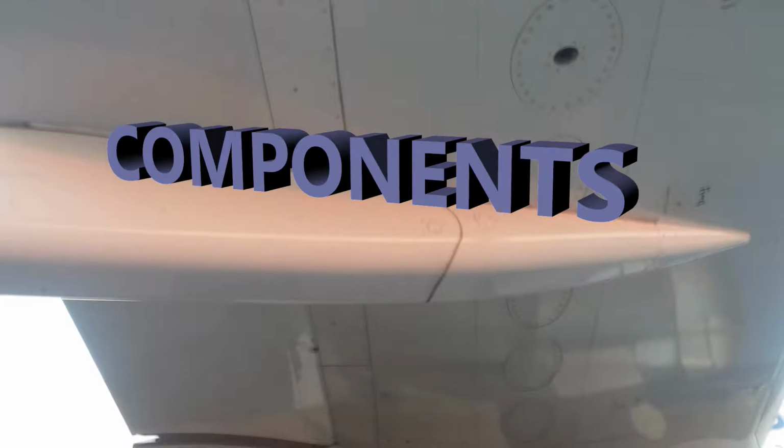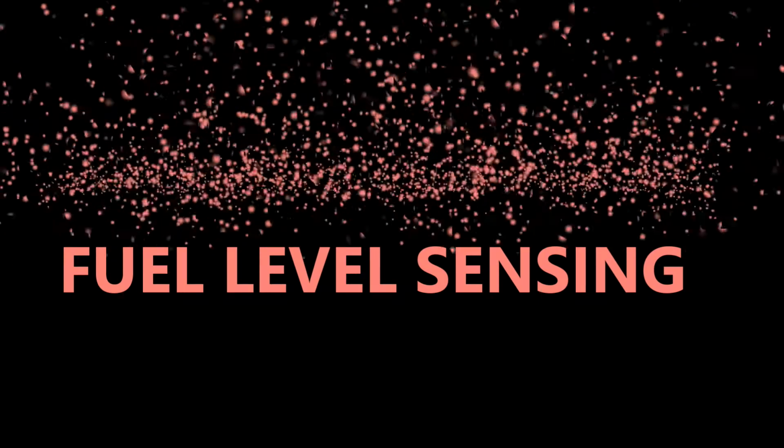Okay, just a little bit on the control units. For the fuel level sensing, you've got the 2 control units, and those are powered by 28 volt DC. Basically, it has a detection circuit to find when a thermistor is in the fuel. Okay, that's just one thing. It's also just fault monitoring.